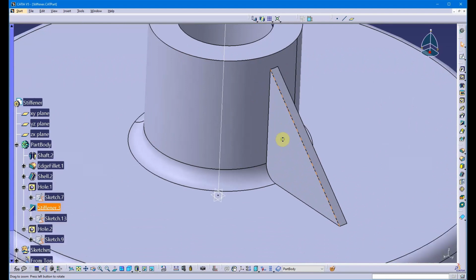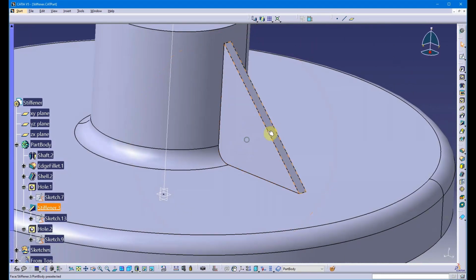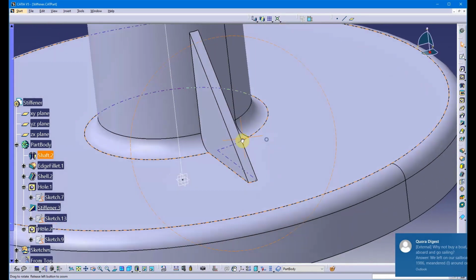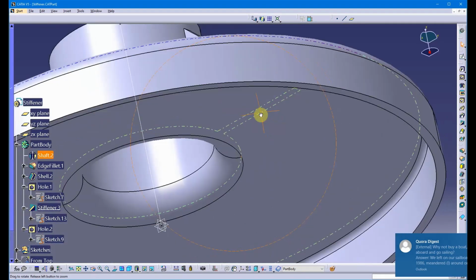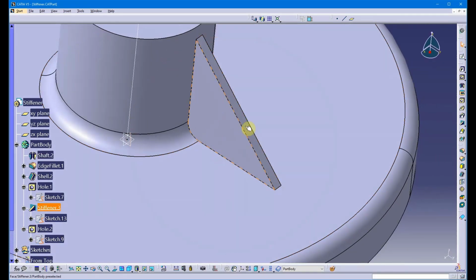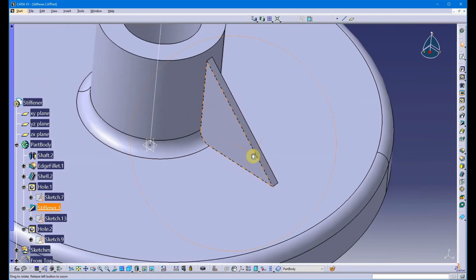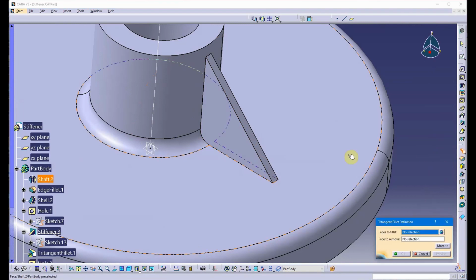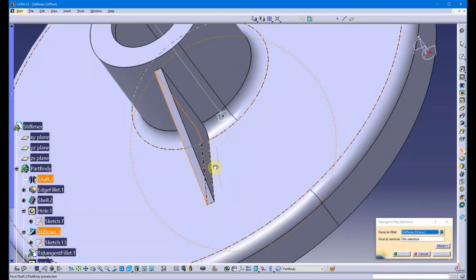What I show my students quite a bit is, notice you've got this rounded here, and that's probably not going to work in a plastic. Well, there's a lot here that's not going to work with a plastic design, but just imagine you want that to be rounded, what CATIA refers to as a tritangent. So I can certainly throw a tritangent on this to round off that top corner.